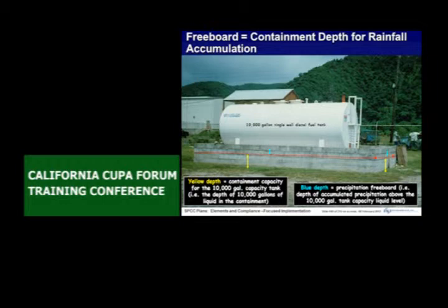Don't forget, this is different than fire code. If this were a tank inside, like a class 1, class 2B, or combustible, if there's sprinklers, if it kicks in with the fire code, say H occupancy, how much water has to be held up for fire code? 20 minutes of full flow. That's a lot of water, depending on how big this is. That's not an SPCC requirement.